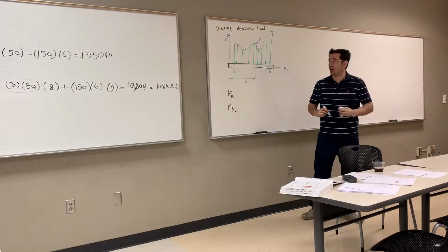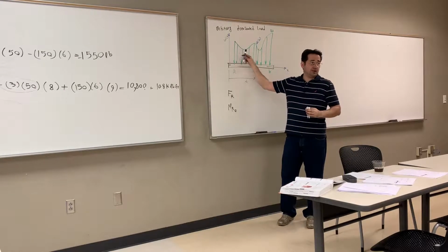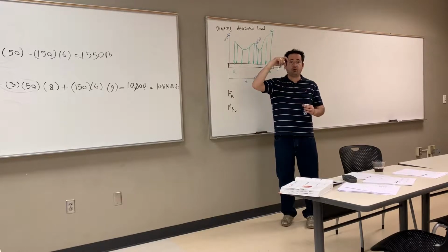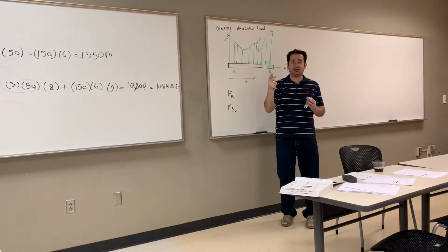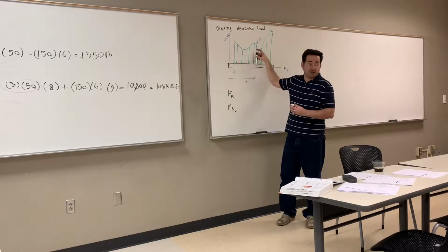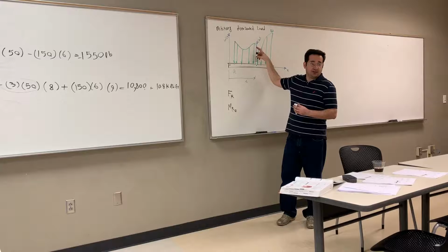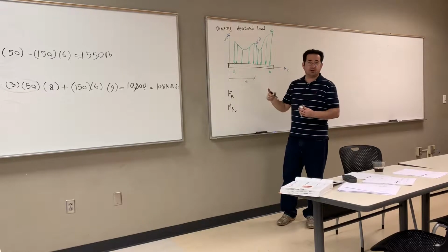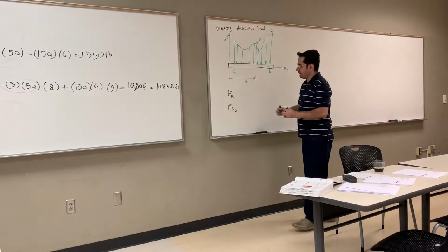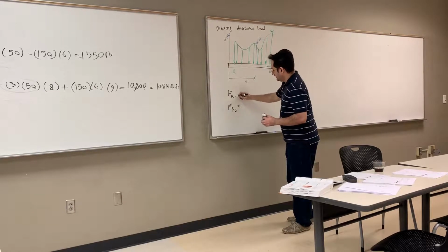Now in the next step, I want to move that force sideways to get one single force that generates the moment implicitly. So at the end of the day, we have one force only at a very particular distance that is equal to all these distributed loads. So you no longer need a moment. So let's first find the value of the resultant force.